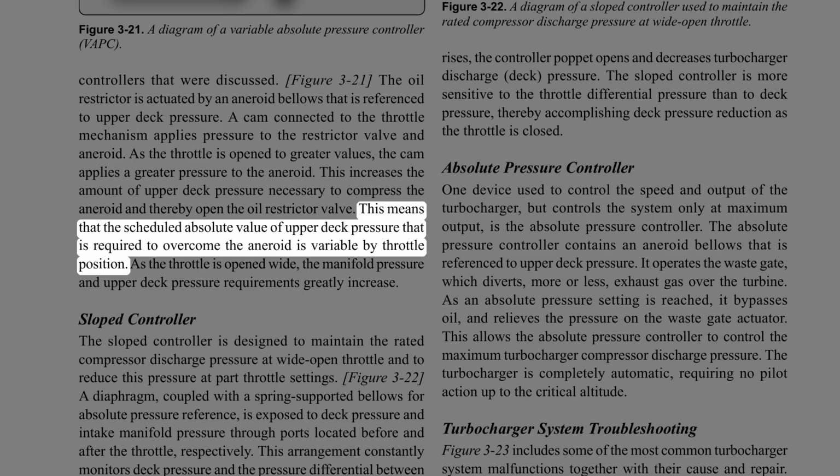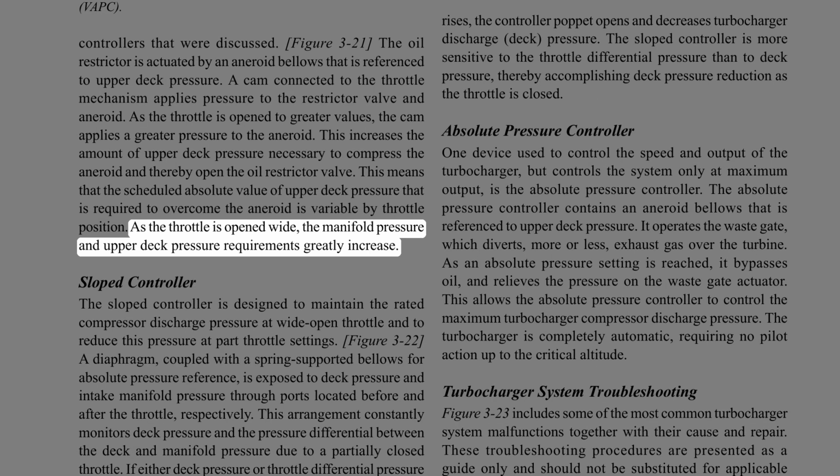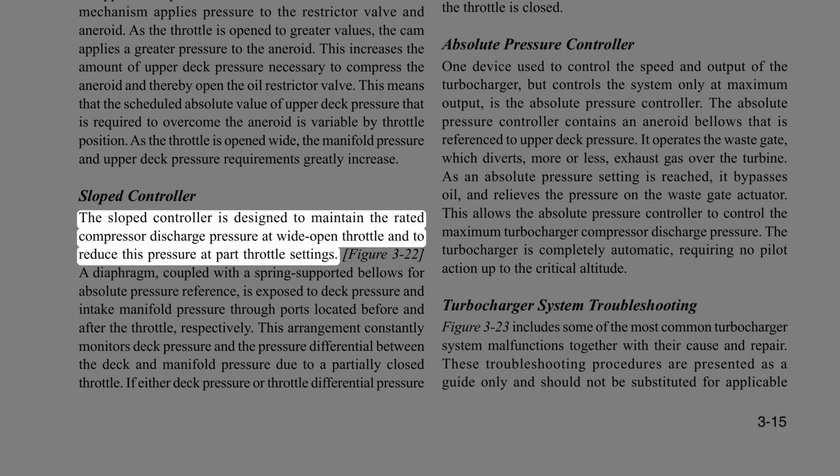This means that the scheduled absolute value of upper deck pressure that is required to overcome the aneroid is variable by throttle position. As the throttle is opened wide, the manifold pressure and upper deck pressure requirements greatly increase. Sloped controller. The sloped controller is designed to maintain the rated compressor discharge pressure at wide open throttle and to reduce this pressure at part throttle settings.